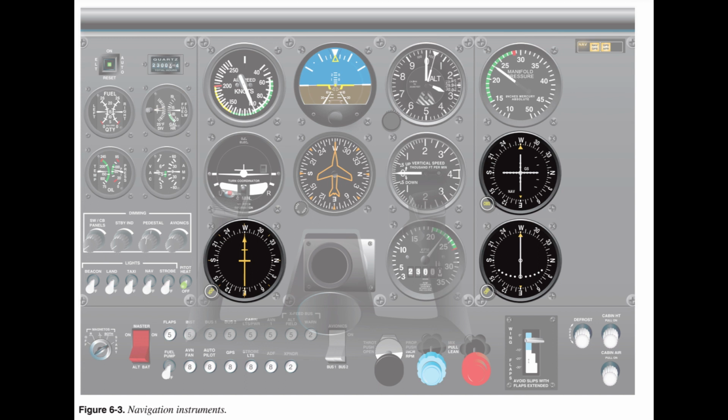Attitude instrument flying using the primary and supporting method. Another basic method for teaching attitude instrument flying classifies the instruments as they relate to control function, as well as aircraft performance. All maneuvers involve some degree of motion about the lateral (pitch), longitudinal (bank/roll), and vertical (yaw) axes. Attitude control is stressed in this handbook in terms of pitch control, bank control, power control, and trim control. Instruments are grouped as they relate to control function and aircraft performance as pitch control, bank control, power control, and trim. Pitch control.